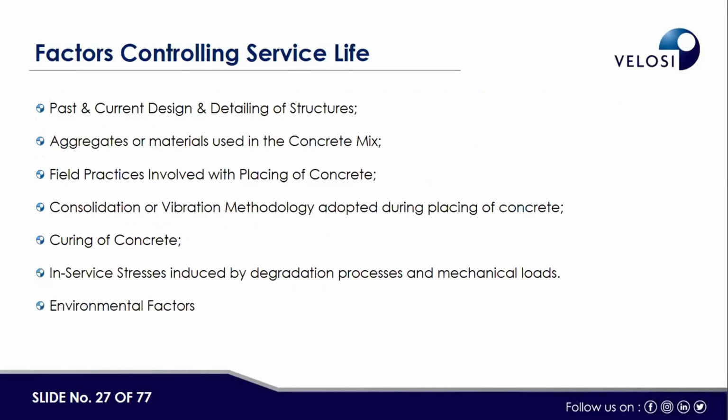Factors controlling service life. As we normally see, this applies from a car or a cycle to any asset under our control as an engineer. We have to look at past and current design and detailing of structures, aggregates or materials used in the concrete mix, field practices involved with placing of concrete, consolidation or vibration methodology adopted during placing, curing of concrete, in-service stresses induced by degradation processes and mechanical loads, and environmental factors. The focus here is mainly on civil buildings.